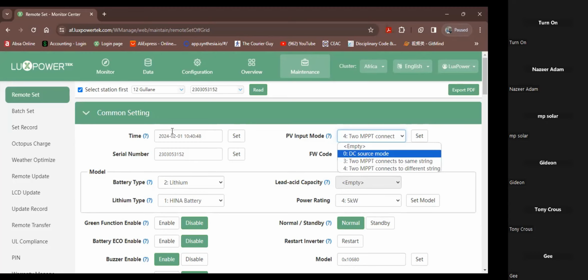This part here about the ISC, I'm not sure about. I'm not convinced about that, because our MPPT rating is peak 20 amps, but max continuous 13 or 15. So I'm not sure what panels or what brand of panels you consider using and what the current is there. But I can advise you that our MPPT has a limit, peak current for a very short time of 20 amps, and then obviously continuous 13.